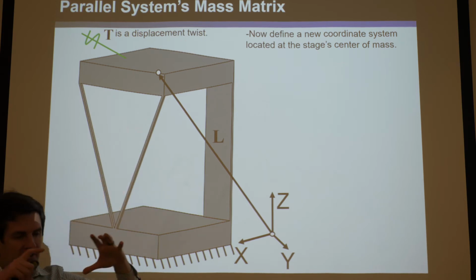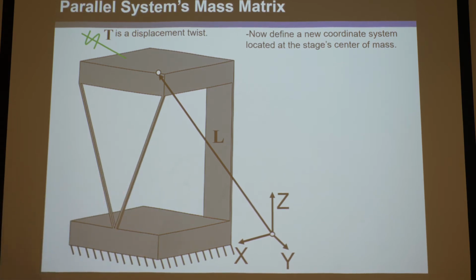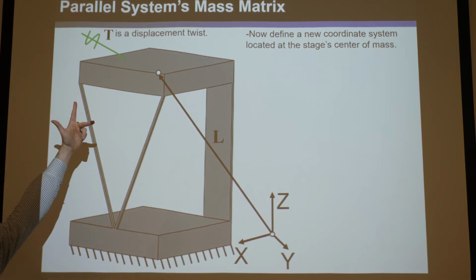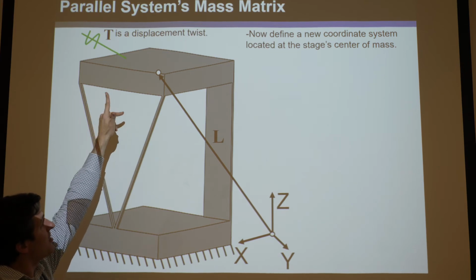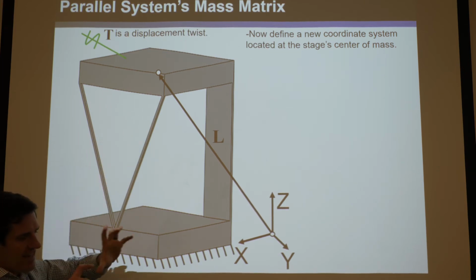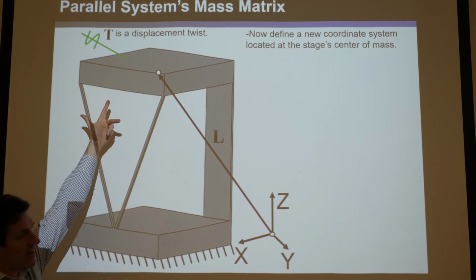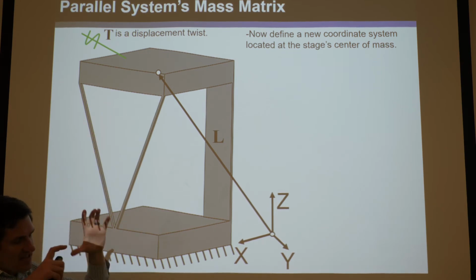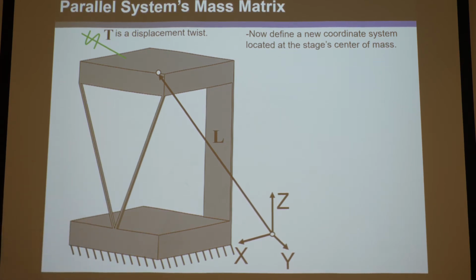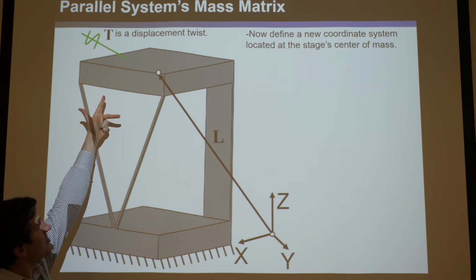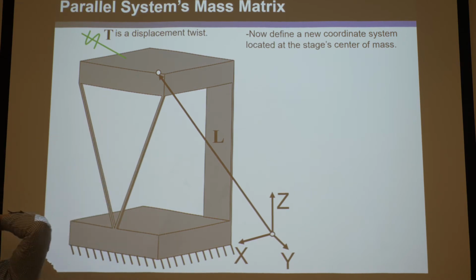and to define that body's angular mass moment of inertia, basically, you would do a 3x3 inertia tensor, okay? And for every point that's located, as you move that coordinate system, you will change the components in that tensor. And you'll find there's always a particular direction at a particular point where that tensor will be a diagonal tensor, and all the components are 0 except along the diagonal. And that corresponds with directions that are called principal directions, okay?